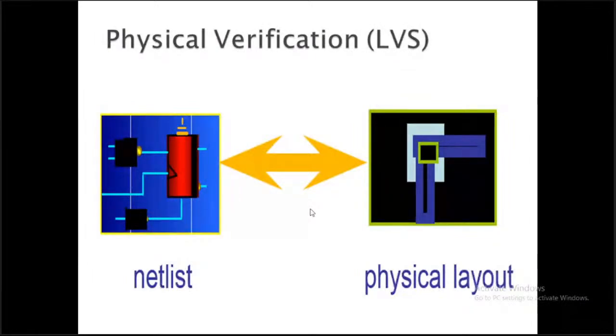After doing this, we now have the physical level data as well. First we had the RTL code level data, then we converted it into the gate level data, the gate level netlist, which is mapped to some specific technology. Then we went for placement, routing, and then CTS. We did everything. We do the timing closure as well. STA, static timing analysis, we do on that: whether all paths are proper, and whether the functionality is working correctly or not. Then we go for the physical verification of those IPs, whether the layout that is created is correct or not. So validation is needed in every step.